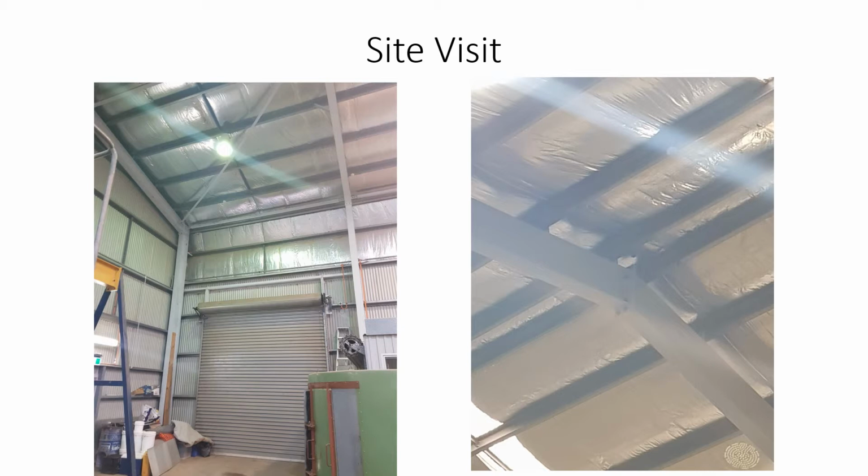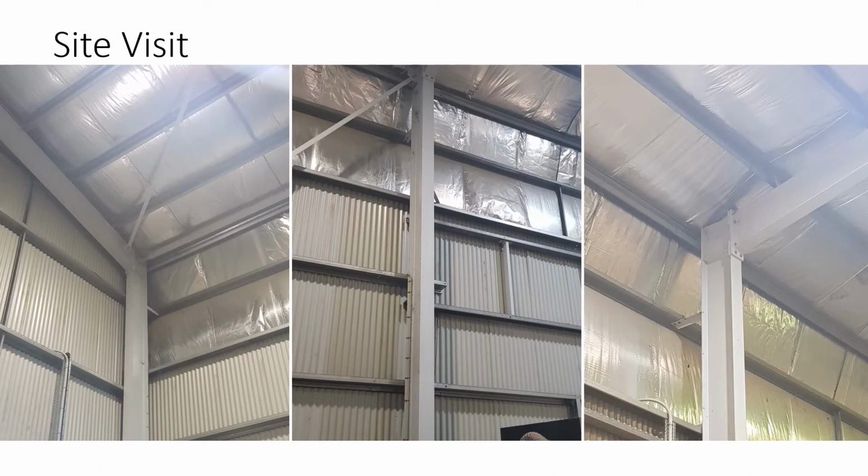Bracing can be angles, rods, or cables in the roof and transmit loads to the foundation. Secondary steelwork are members that connect and restrain the primary steel frame. It includes girts for the walls and purlins for the roof, which support the roof and wall cladding, and transfer loads from the cladding to the primary steel frame. The basic connection members of industrial building and shed are apex connections, corner connections, and base connections. They provide connections between rafters and columns and footings respectively.